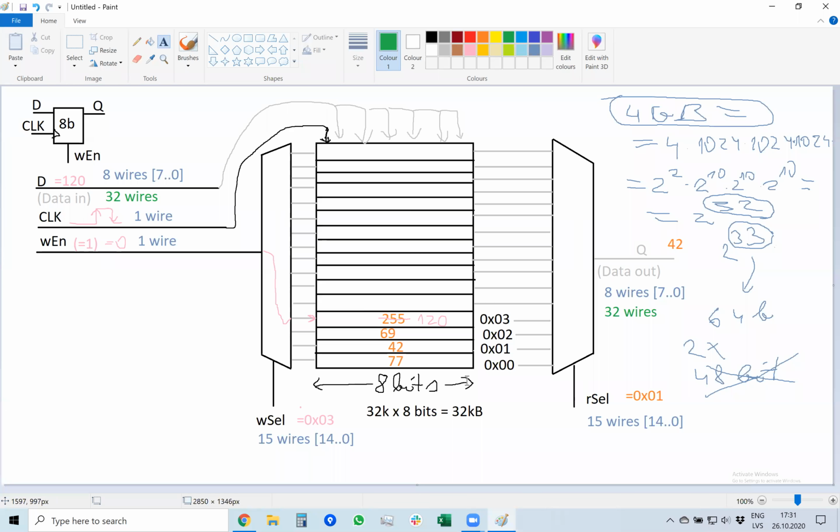And this is why the memory is made in such a way that you select a byte, and these numbers, for example these 32-bit numbers, need to start with an address that divides by 4.